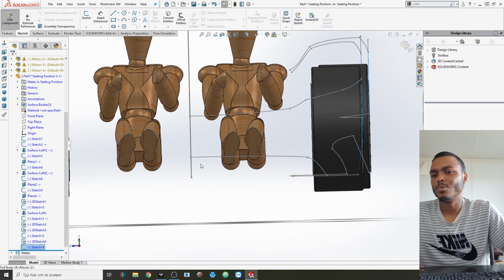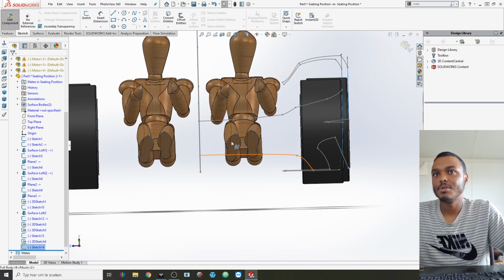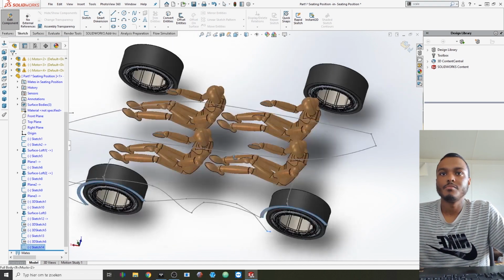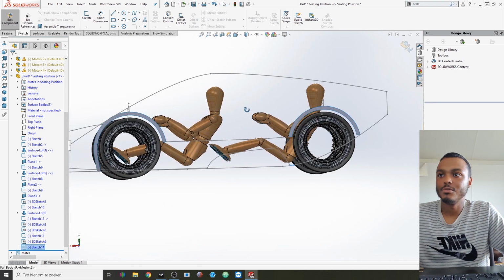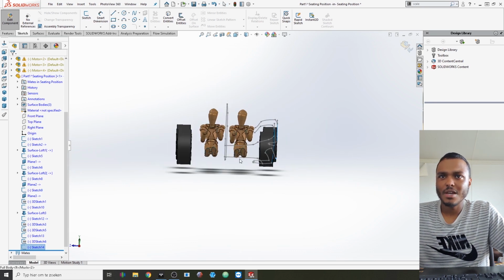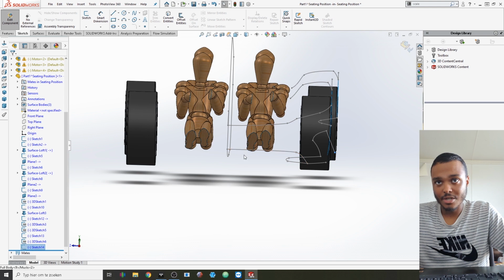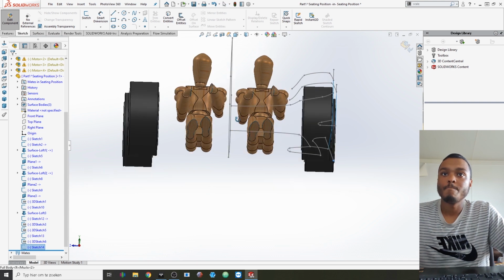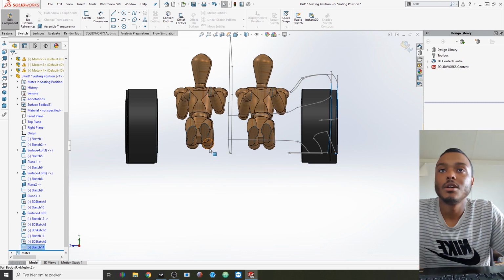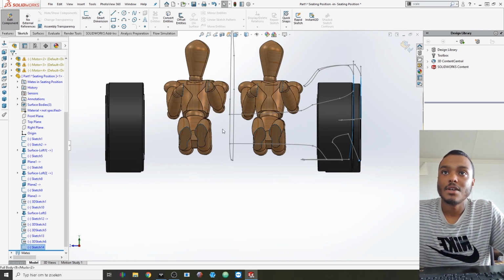But I was also saying that I want to put the batteries right there. So I need to make a consideration of what would be the optimum position for everything before I do those things. I think I would still have space in there too, if I make a transmission tunnel that has 2 layers to it. One of them would be a little bit of a double bubble situation that, like I said, would have the actual aerodynamic effect, so you would be able to keep the frontal area down, but the other one would be just to house the battery, so it would sit up there.